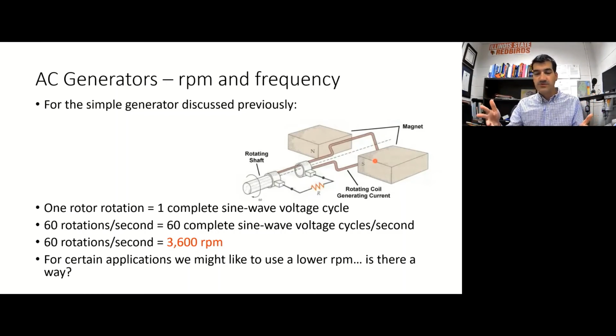So you could use a really big gearbox inside the wind turbine to take your slow moving rotor blades and step up the speed to a really fast spinning generator. But gearboxes are not 100% efficient, so you'd prefer not to use a gearbox that has that large of a gear ratio if possible.